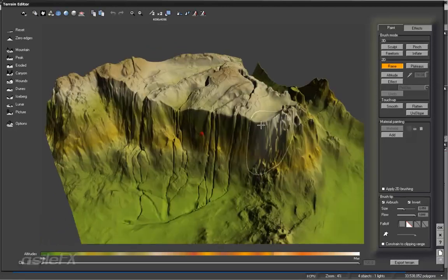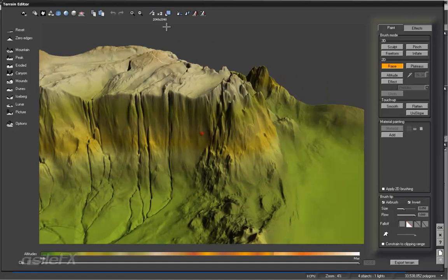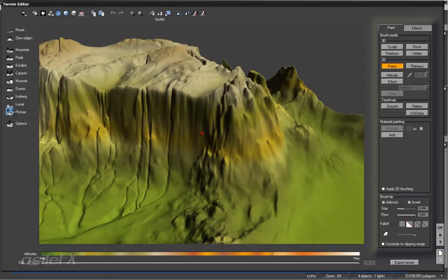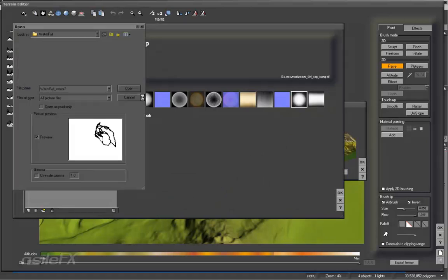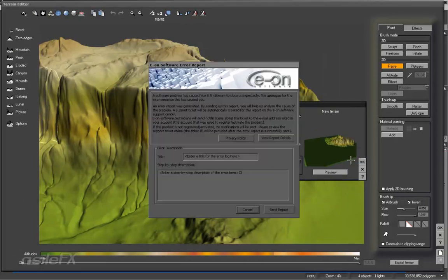I've noticed a few problems with the painted texture maps. We'll have to see. But it did work before, no problem. So I'm going to go ahead and just downsample this once again to 512, go to the picture, and we can load back in that saved image. Go to Subtract, set it to 30, and click OK.